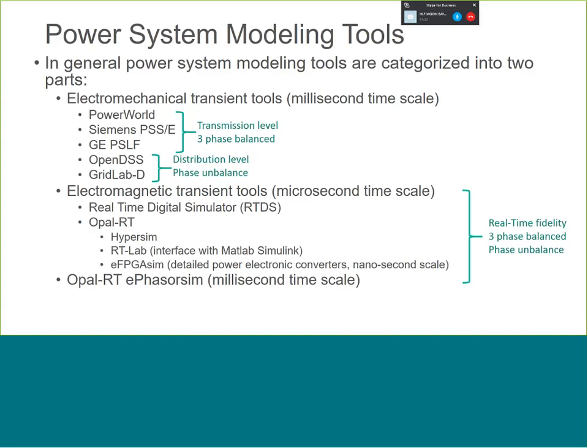One unique tool that we have is Opal-RT's sub-module. It's called ePHASORsim. It is sort of a combination of real-time tool, but working on an electromechanical scale. So you would think of it as a PowerWorld level solver, but being able to talk to external devices, connect to external devices, do communications. But if you are concerned with large-scale systems, 50,000 bus Eastern Interconnect, and you want to have wide area measurements on it, you can use ePHASORsim and get that capability out.